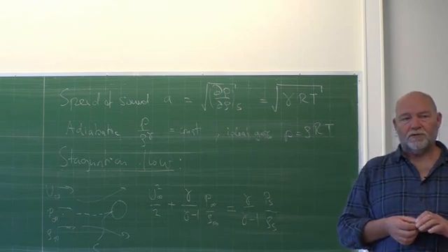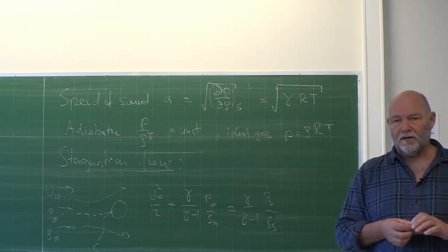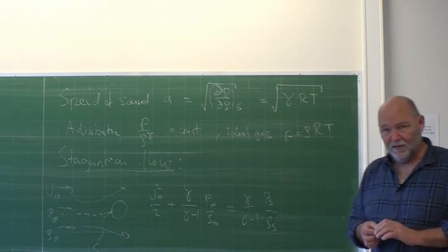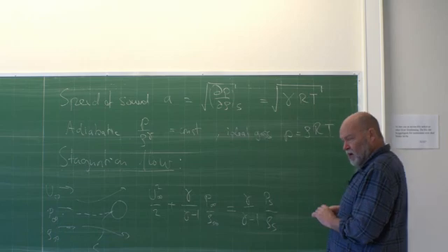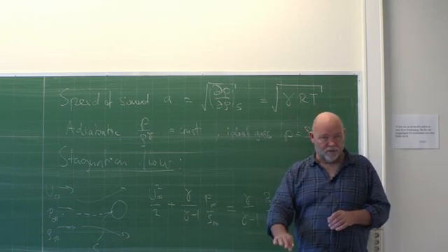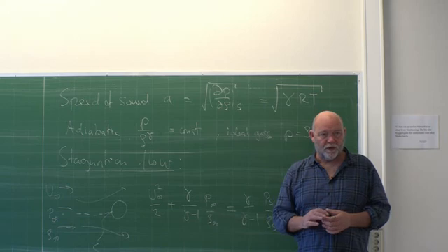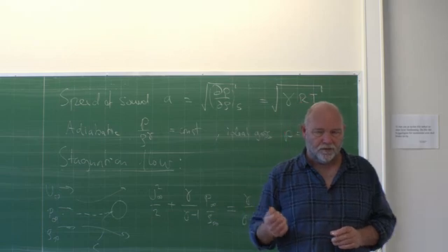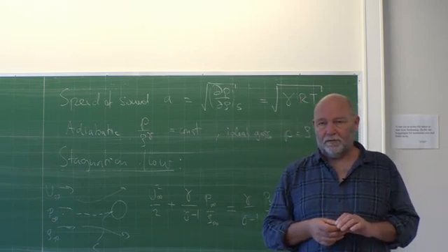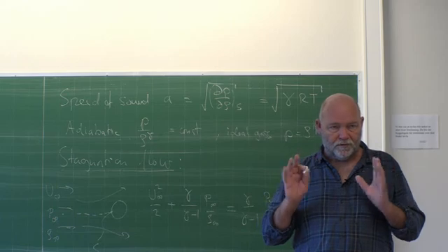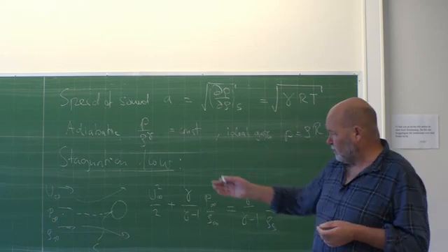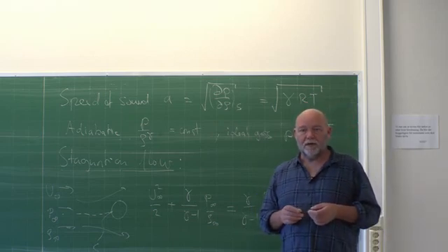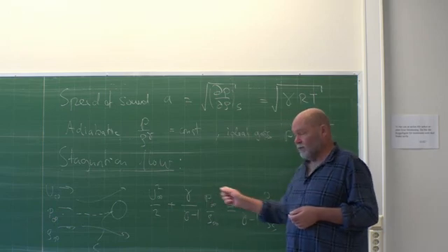The Bernoulli equation is, I guess, the equation that is most violated of all the equations, because you have a long, long list that has to be fulfilled before you're allowed to use Bernoulli. One of them will be either your flow has no vorticity, the curl should be 0. We can't really say that here. Or you have to move along a streamline. Your 2 points have to be on the same streamline.